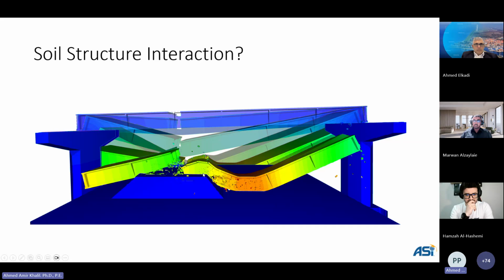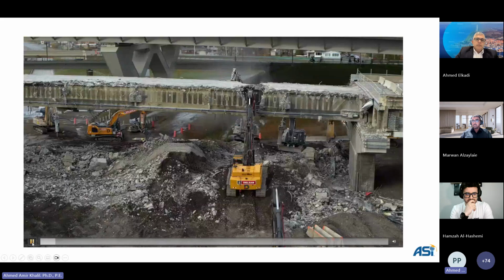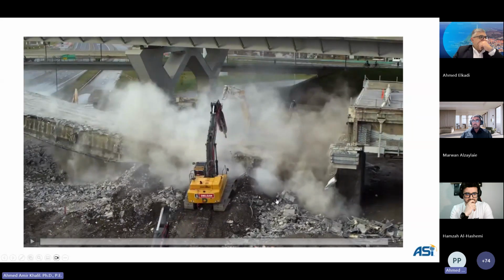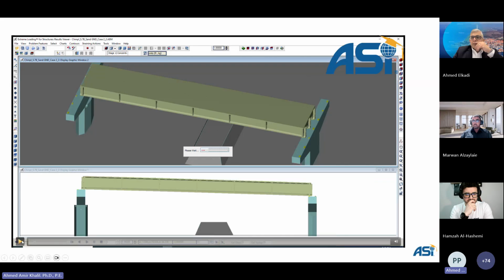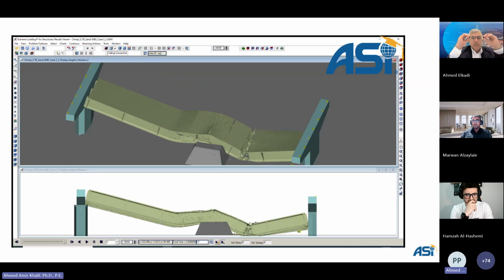So again, we did sensitivity analysis with multiple berm sizes, and we changed the demolition scenario different times in order to get to a case where this impact does not cause that pier to collapse. And this is the analysis that we provided ahead of the actual drop.